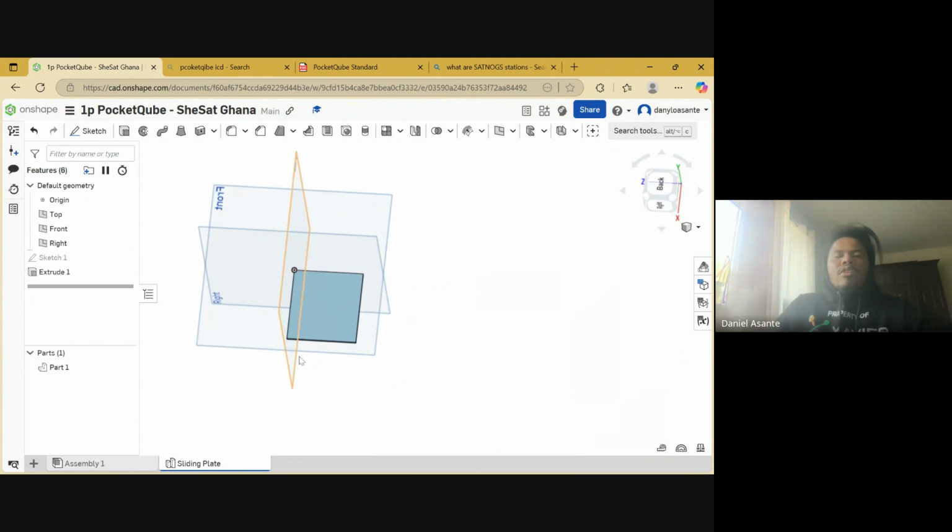Now we are going to create the... Is that just stuck on inches? Yeah, I was thinking, so if you have this button here, show measure details at the bottom here at this side, where my mouse is, when you click on it, you can change it. Length is here, length units, and then you can click on millimeter, or if it's in foot, you can change from foot to millimeter, and then it will change all the dimensions.